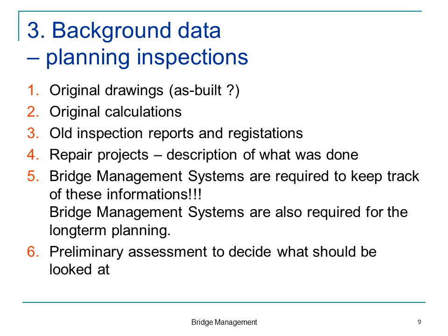It would be nice and useful to have the original drawings and calculations, because suppose there's a corrosion problem somewhere, then you would like to know if that was an area where you really need all the reinforcement, or an area where there is 3 times as much reinforcement as you really need.